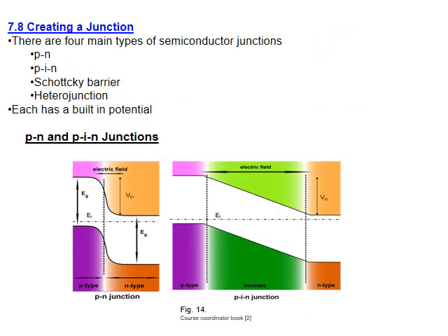Okay. Now we have p-type. The junction could be a PN junction, a PIN (intrinsic) junction, a Schottky barrier, or a heterojunction. I am going to explain them. A PN junction is simply where we put P and N together and create the junction here. P is a higher energy level and N is a lower level here, as you can see. And when we put intrinsic material in the middle between P and N, we change the characteristics, how it will perform. So the electric field here increases.